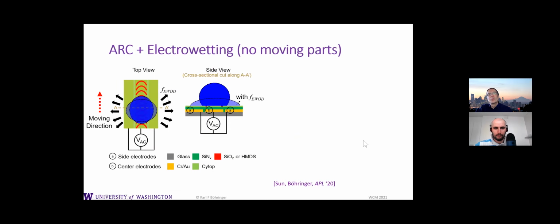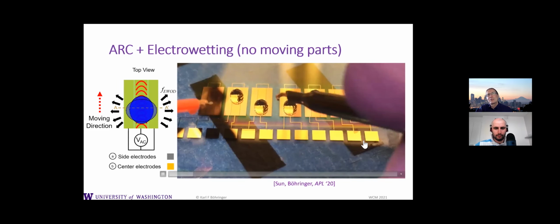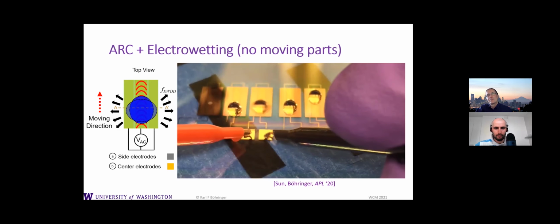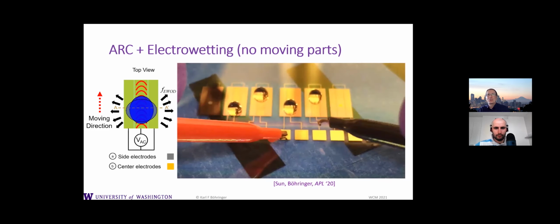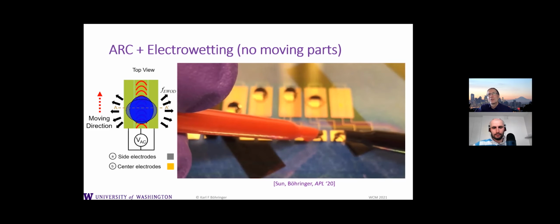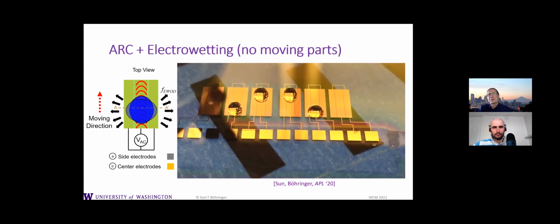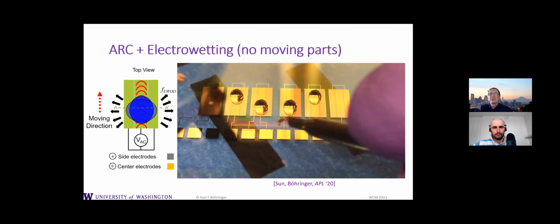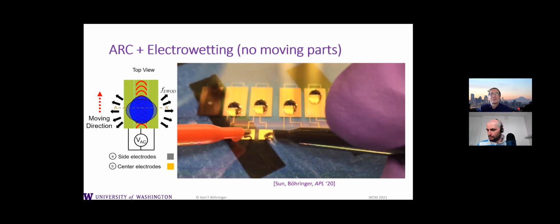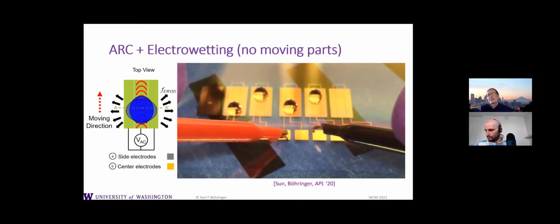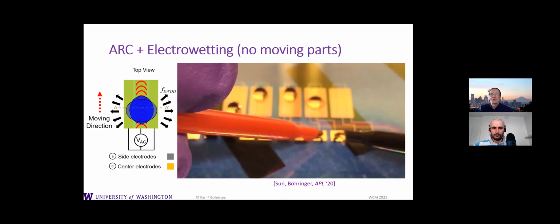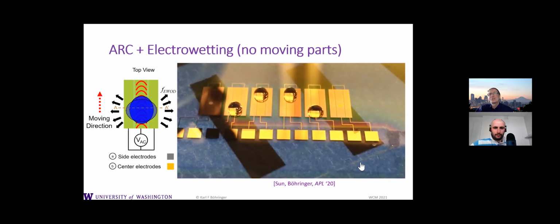Just a few more words: besides vibration, you can also create systems where these drops are moving with electrostatic forces. So it's a combination of these ratcheting patterns, anisotropic ratchet conveyors, and electrowetting, where we're driving the drops in particular directions. Here we demonstrated that we can move them in opposite directions depending on how we pattern the surface. Now we're currently looking at larger scale applications, working with solar panel manufacturers for cleaning large solar panels. This is work in progress.